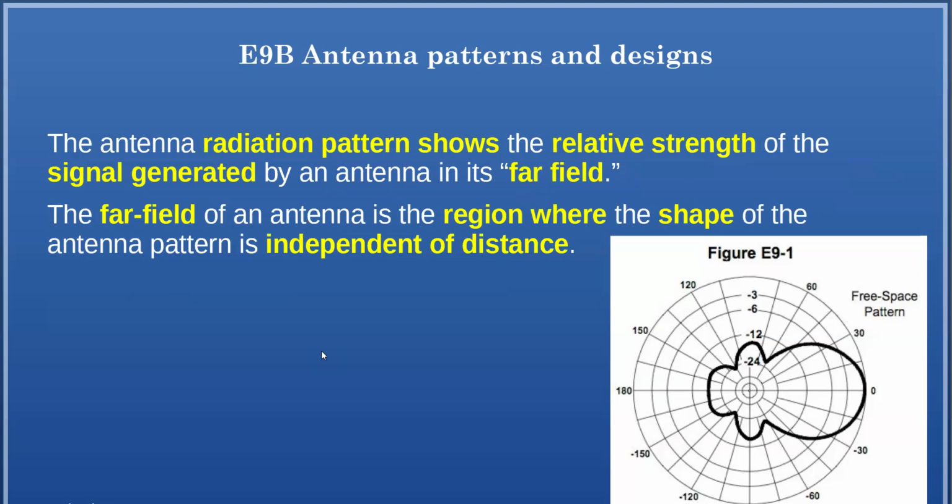These really only show what's called the far field pattern. When you get into what's called near field, it's just a jumbled mess because there's all sorts of things that interact. So you have to be far enough away from the antenna where you have a stable radiation pattern, and they call that far field. Exactly how far that is, I'm not sure, but it will have to do with the wavelength that you're operating at.